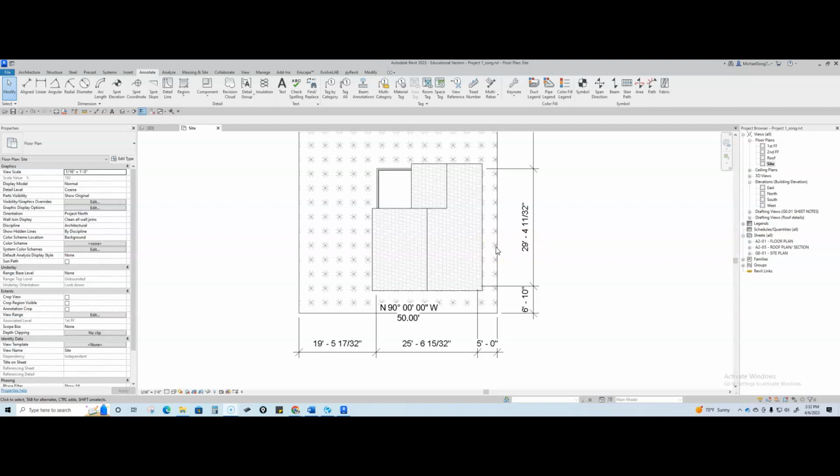So this is an ADU, so in California, ADU setback guidelines are 4 feet on the side yard and 4 feet in the rear yard, right? So technically, we could have actually built this structure 4 feet away instead of 5 feet away. I could move it this way 1 foot, and then in the rear, I could push this house back.